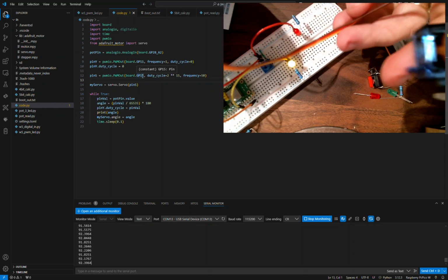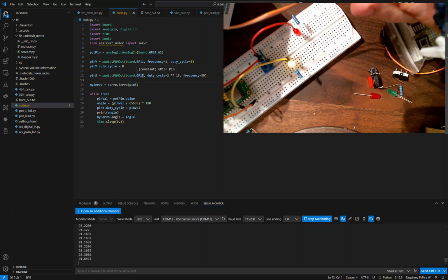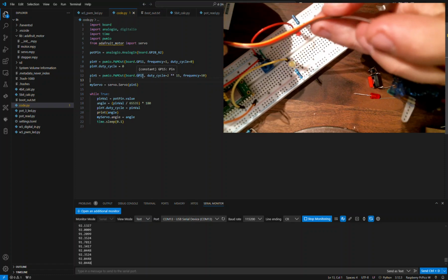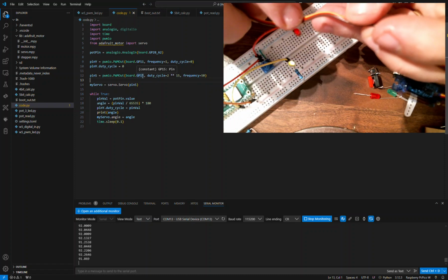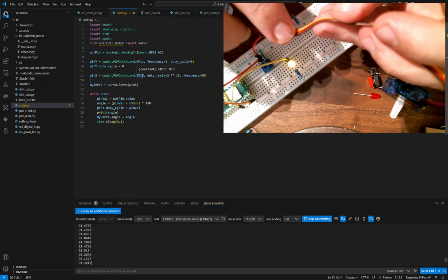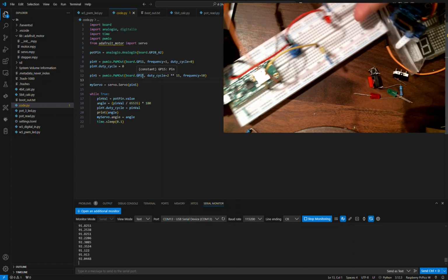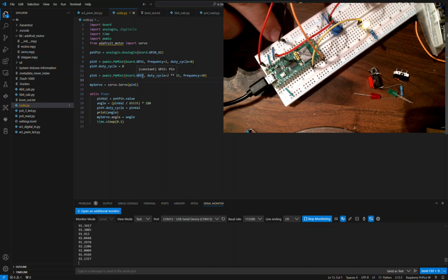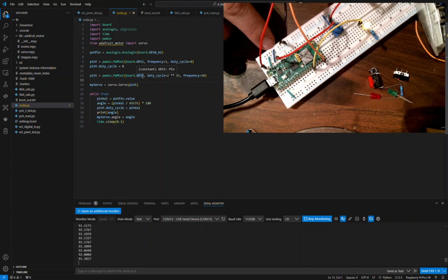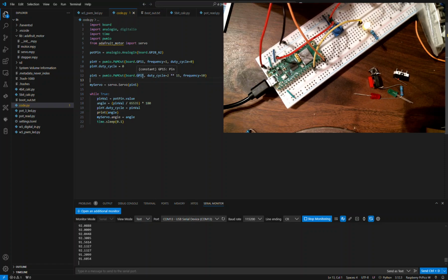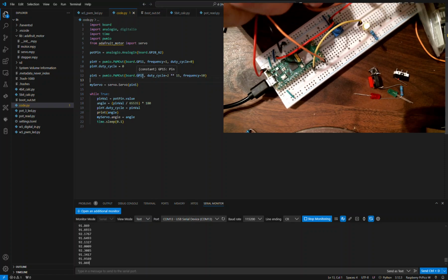All right, the way that you wire up a servo is also really important. It has 3 wires. We've got yellow, red, and brown. Brown is going to be your ground, kind of rhymes-ish. So brown is ground. So that's just going to use your normal ground rail if you have one set up. Or the ground pin is the 3rd pin on the right here.